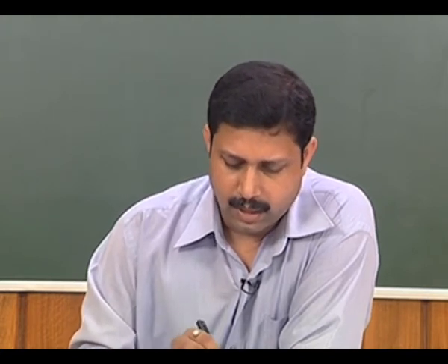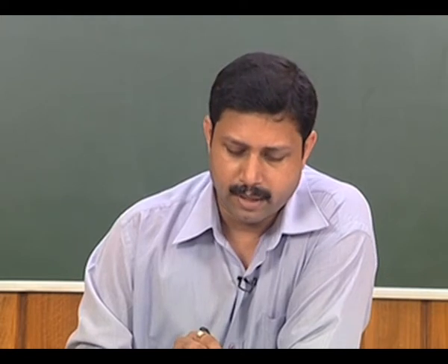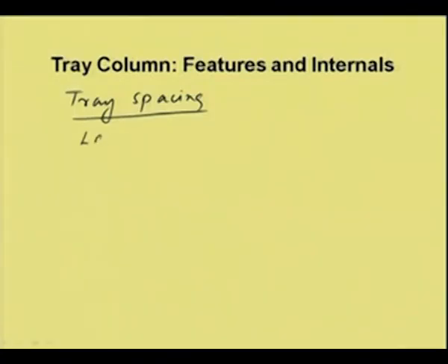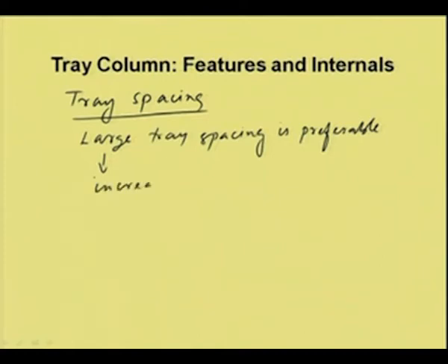So, larger spacing is better, but large tray spacing is preferable yet increases tower height.